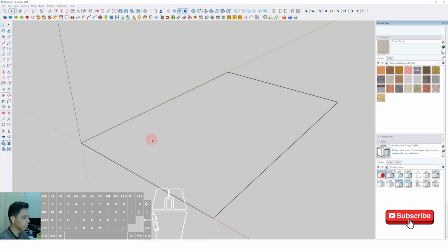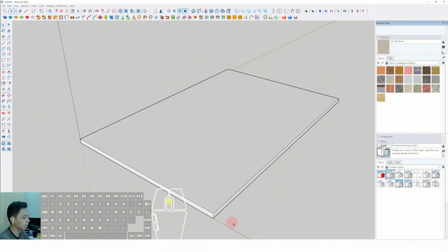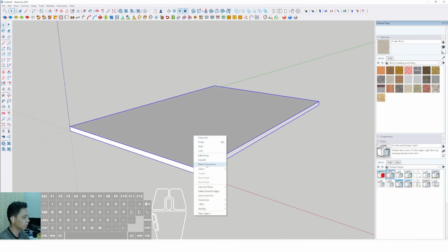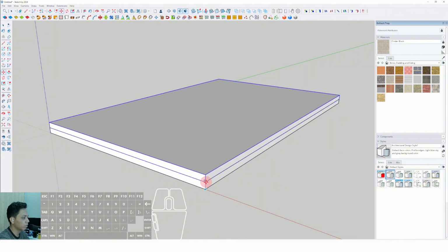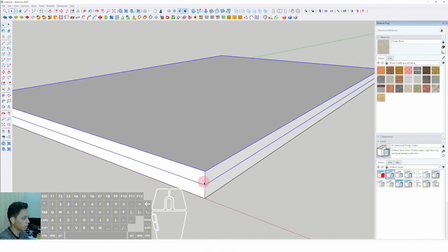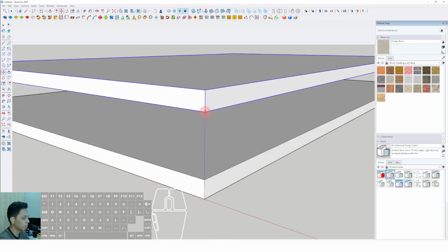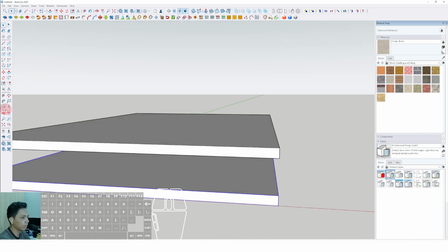Okay, then we can just click this plane, select push tool around 1 meter and enter, and triple click, right click, make group, and make component, right click, make component, create, select a move, press Ctrl, place to this position, and okay, then we can set the floor to ceiling, select a move, and move to the upper position around 3.6 meter. So the floor to ceiling is around 3.6 meter. Okay, and I will show you about the dimension.